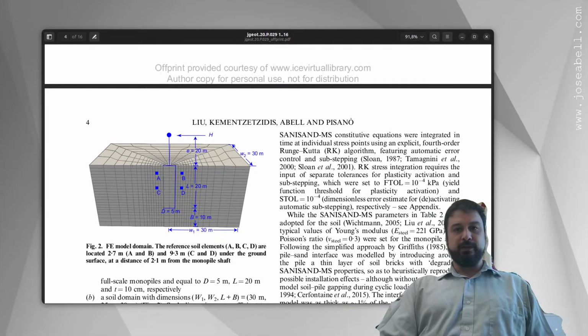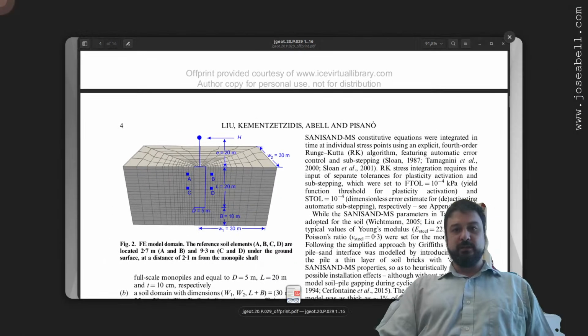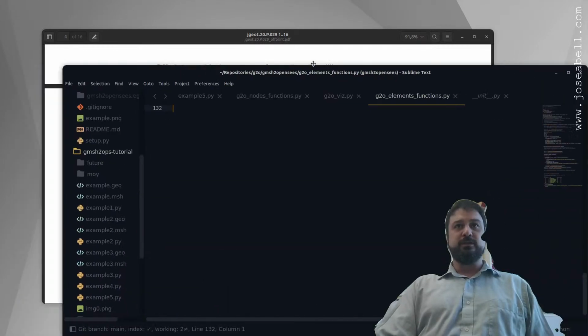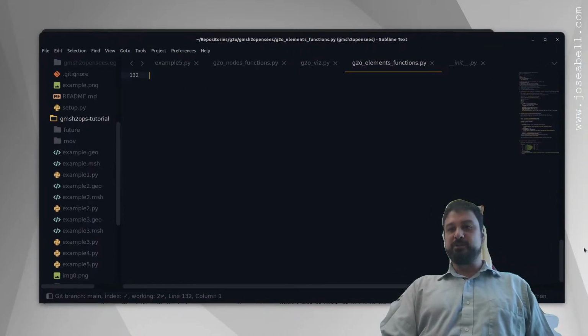So bringing up Gmsh to OpenSees, we are going to want to create a Gmsh model. The other thing I want to do is upgrade this to use my new 10-node tetrahedron elements, which are pretty nice for soil problems.